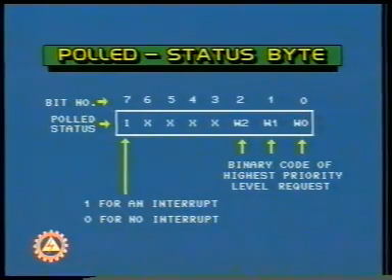The most significant bit D7 indicates whether the interrupt is present or not. A logic 1 in the most significant bit indicates the presence of the interrupt, and a logic 0 indicates the absence of the interrupt. Thus, the microprocessor polls the controller rather than each peripheral. The polled command can be issued by the use of an operational command word.